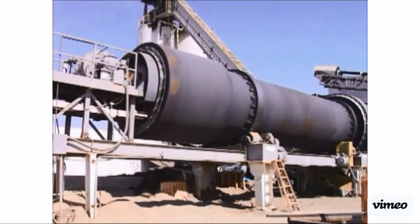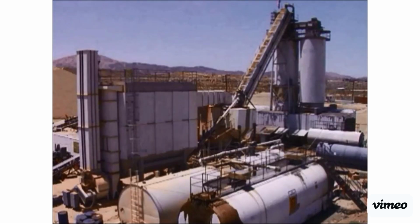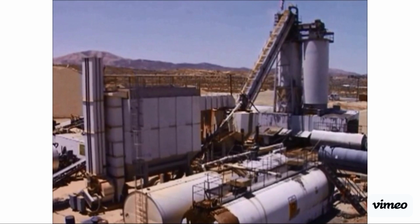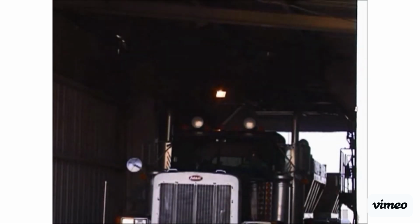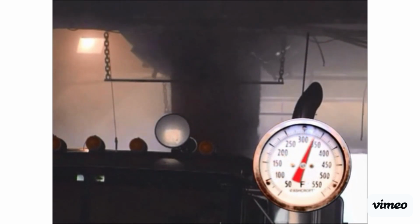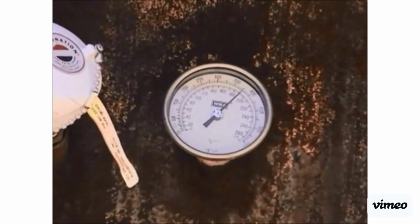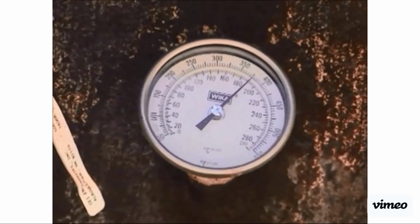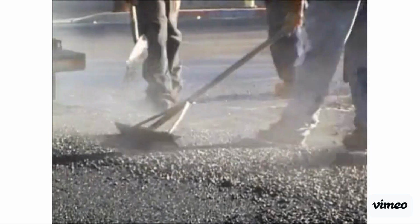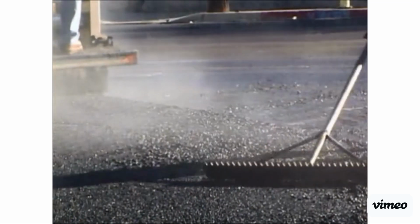The RAC binder and aggregate are now combined using conventional HMA processes. The RAC mix produced is now stored in silos, ready for delivery to the job site in trucks. Temperature of the material at this point should range from 320 to 335 degrees Fahrenheit. Temperature management is essential to successful RAC mix placement and compaction. It should be noted that high-viscosity RAC mixes are very sticky, have a rubber odor, and are not conducive to large amounts of handwork.